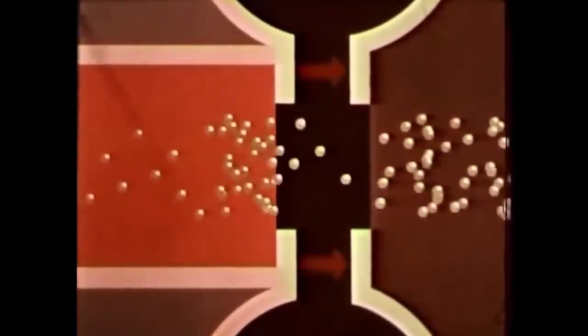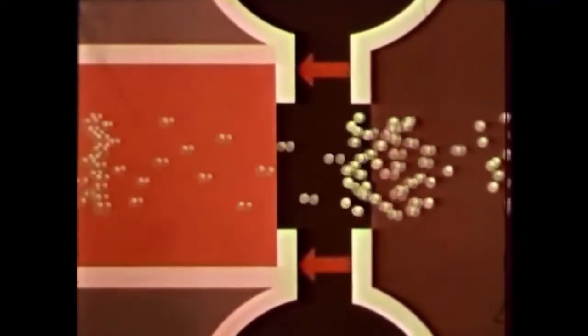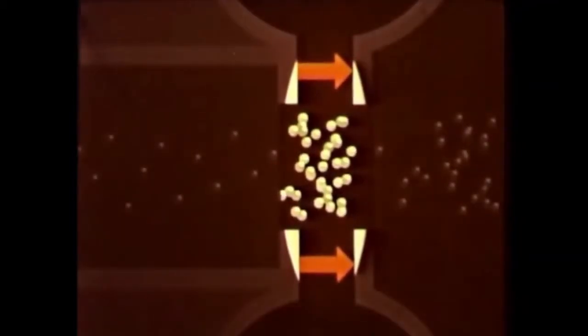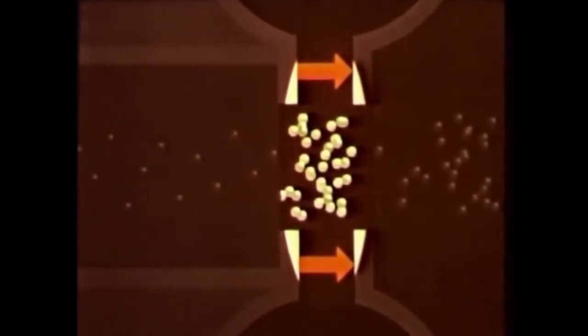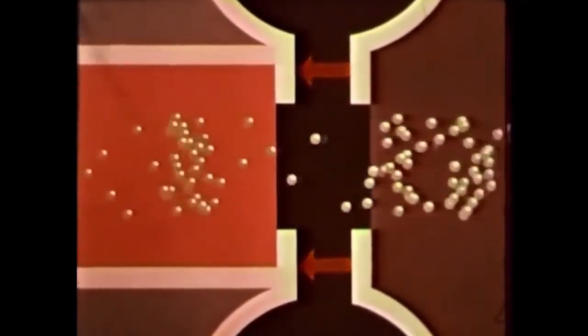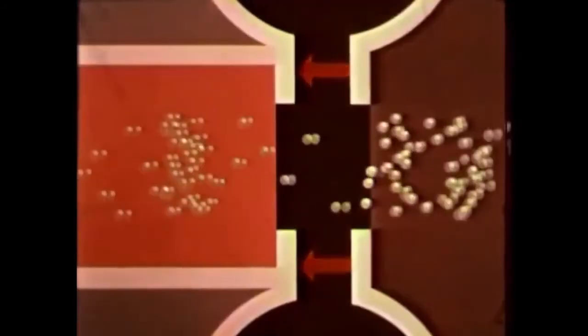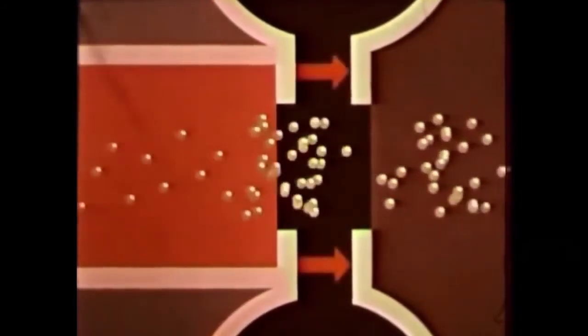At the second resonator, however, the majority of the electrons are in bunches, and these are decelerated. Only very few electrons are accelerated. The result is that almost all the kinetic energy is converted into electromagnetic energy, the electromagnetic energy of the field which produces the output signals.